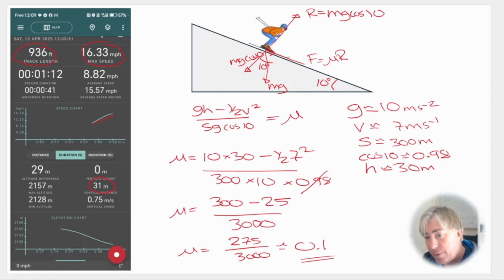So I've literally just been rooting around on the internet to look for the frictional coefficient of skis on snow. There's a variation of published values depending upon the condition of the snow, temperature, and the condition of the skis, and so on. But of course, that's a whole PhD waiting to be written. So I'm just going to go with what I found. I discovered that the most commonly published value was anything between 0.05 and 0.1. So that was our frictional coefficient range of skis on snow.